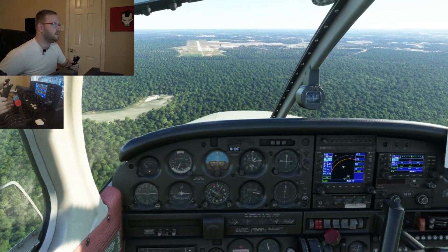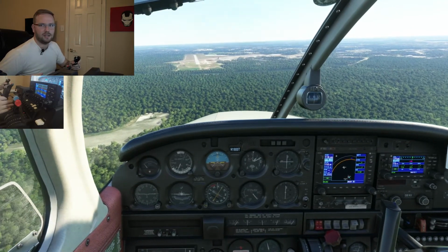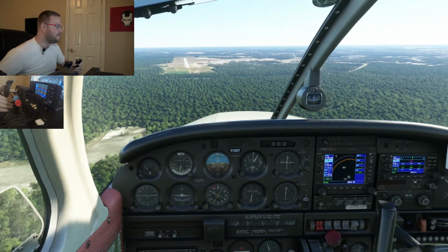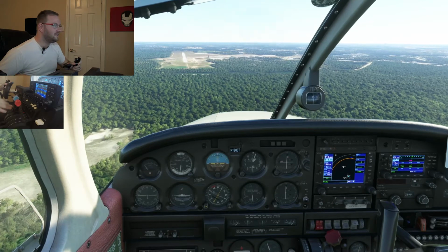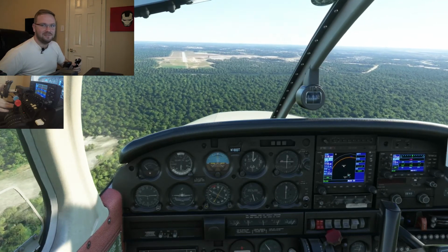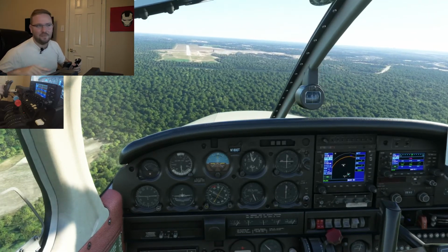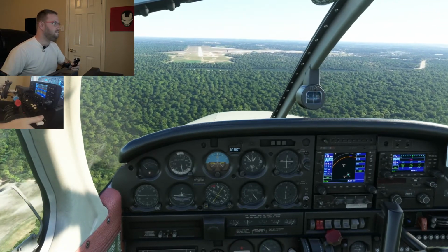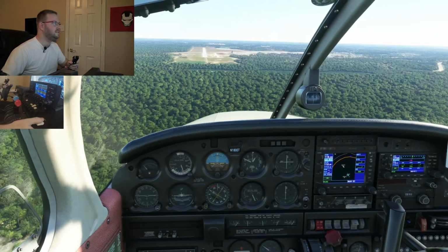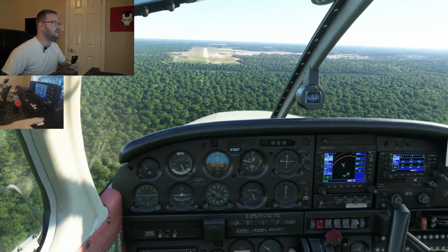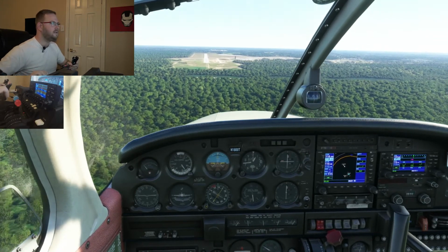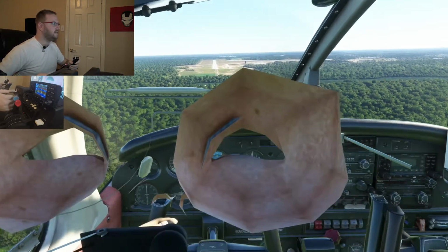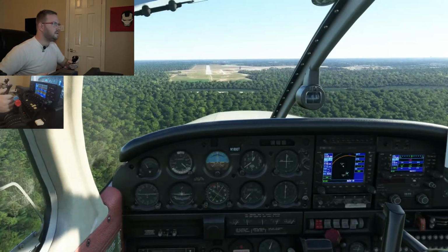We've been cleared for a touch and go. Or actually, he's a clear to land. I'm not good at simulating my own radio calls. We're going to do a touch and go. Just pretend that the rest of the calls all made sense, okay? So we're inside the white arc, going to go flaps 1. Still high. Still pretty fast, but we're dumping it down. 500. Flaps 2. There's red over white, so we can go ahead and lower it down, slow it down a bit here.